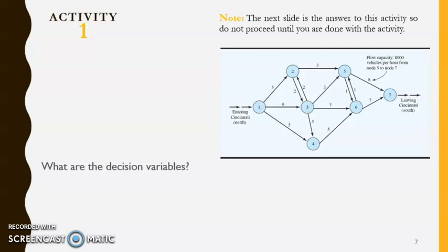For example, if we have road 35, if the model tells us, okay, take road 35, it's not enough, because road 35 has the capacity of 3,000 vehicles per hour. We want to see, when we consider 35 as an active road, how much load must be put on this road.